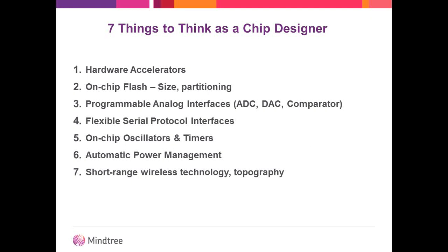The sixth is automatic power management. Today a lot of chip companies build in a lot of infrastructure for power management. You bring in oscillators, timers, low power modes, power gating, and a lot of different techniques are brought in as infrastructure. But what you really need to look at as a chip designer is how it is actually being used. Have you looked at use cases of how, for example, automatic power cycling will happen?